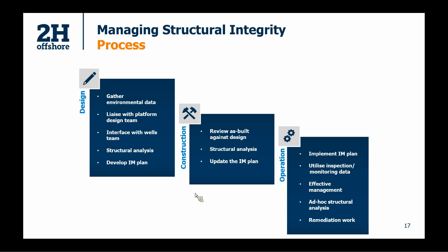The next important stage, when you come to construction, is to actually review the as-built system against the design. It's all very well having an IM plan, but if your system differs significantly between the as-built and the design, the IM plan that you created at the design stage may not be relevant to the system that you actually have in reality. So review the as-built against the design, and if there are significant changes, then you would need to go back, update the structural analysis to see if you're changing the severity or the location of the integrity issues, and then update the IM plan again.